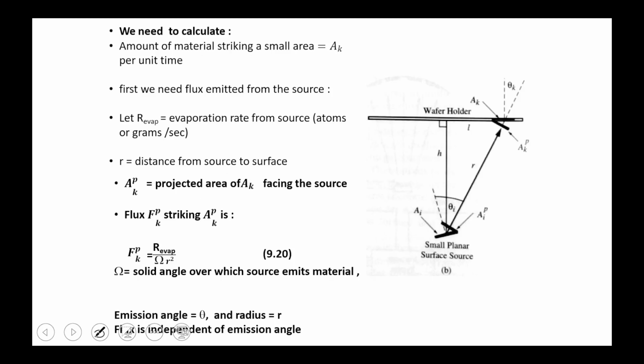This is how to calculate the striking of atoms on the area. This is the formula, the relationship between flux and striking. So how much the rate, how much the distance: we have to optimize all these things. How much deposition time we require, how much RF supply we have to give, 10 watt, 100 watt. What is the distance between the target and substrate holder? It is recommended by people to keep around 7 centimeters. In some cases we have to put 5 centimeters also.